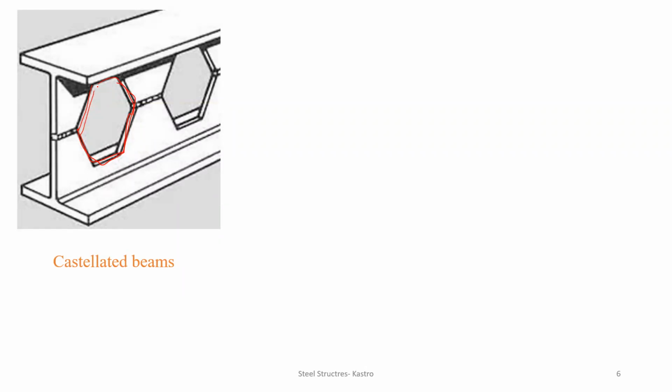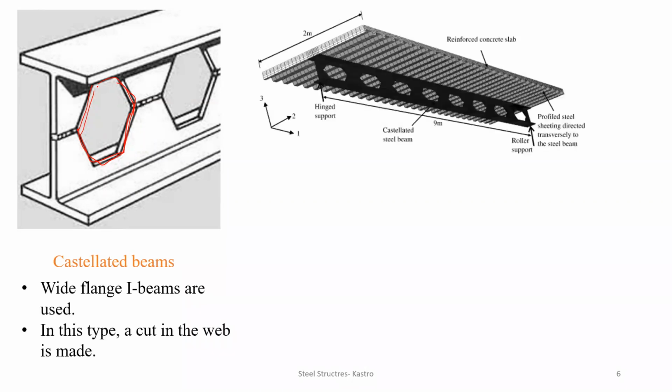They can be used at the places where you are going to expect a very small amount of loads, but at very frequent intervals of time, right? Remember, very little load and at very frequent intervals of time. So those beams are called castellated beams. I'll show you a couple more figures regarding the castellated beams.